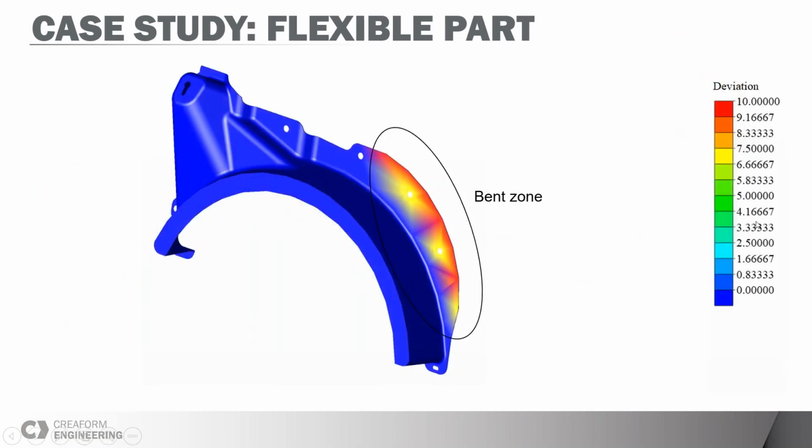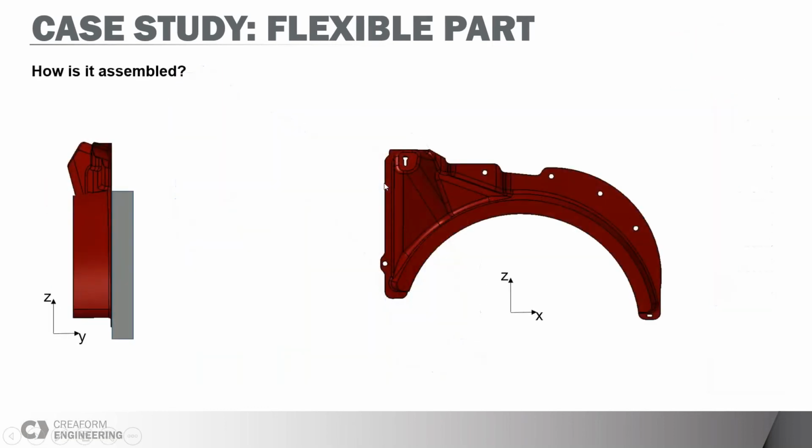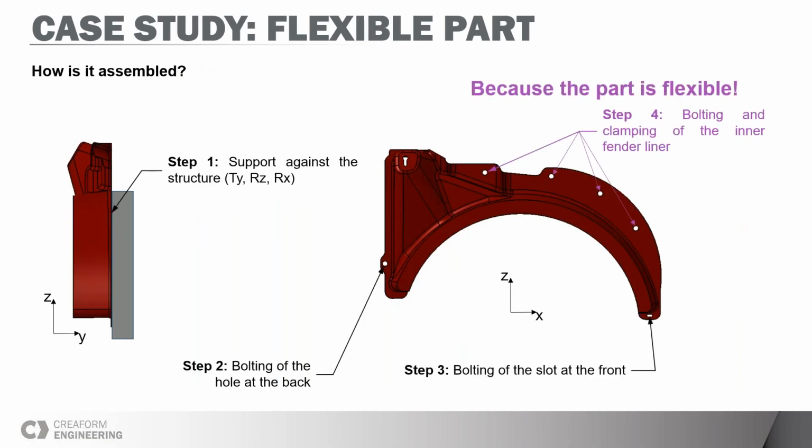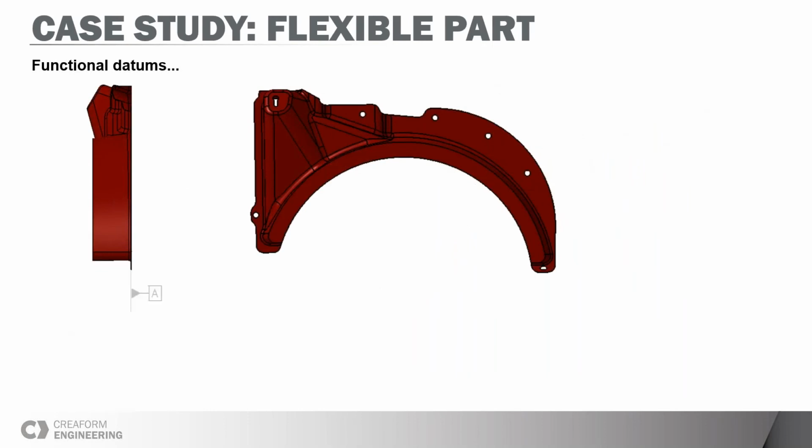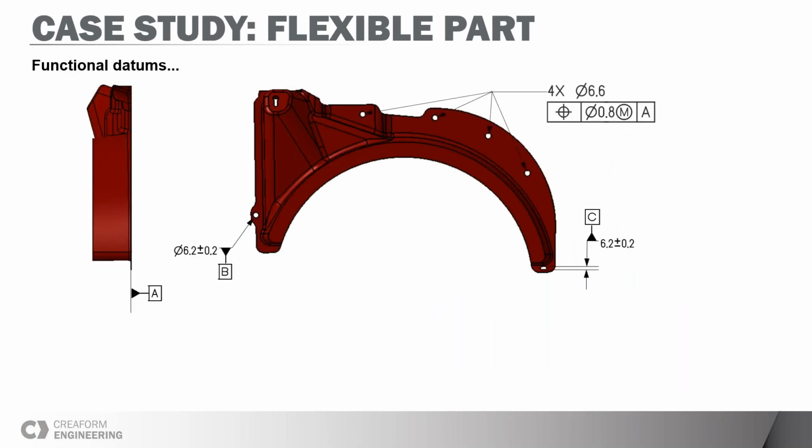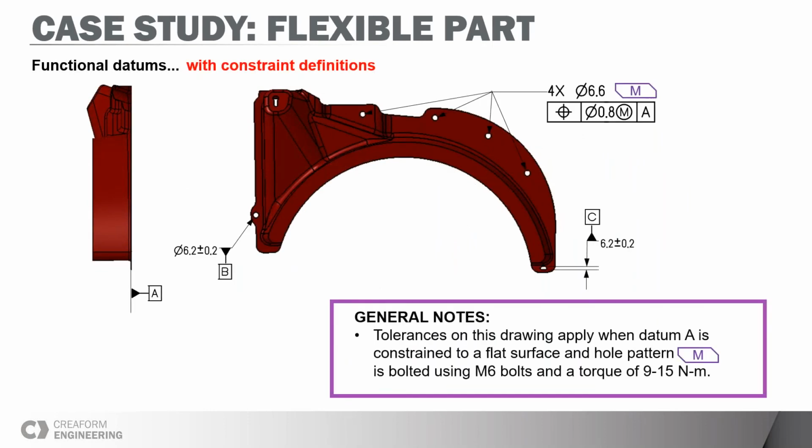Yeah, and at Creaform, we do a lot of inspection services, with people sending us samples, like 30 part samples for first article inspection or the PPAP process, and it's always the same thing. You make a setup where you can put your datums at 0, and then you have to over-constrain your component, which is flexible, like Cedric showed in this specific case with the 4 holes that need to be bolted.